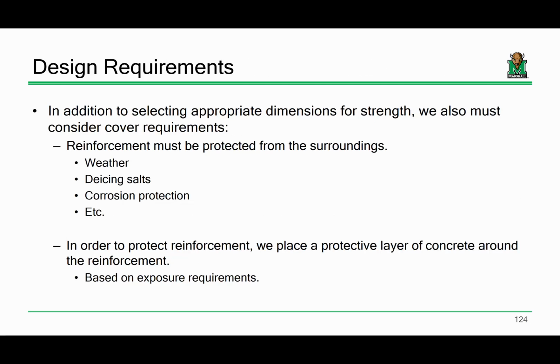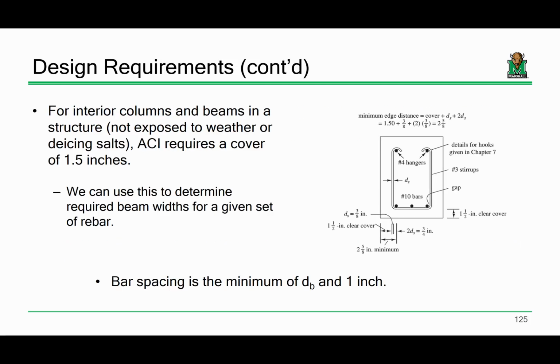The issue that I want to mention now is the issue of cover. Okay? So has anybody ever done any work with concrete or anything? Does anybody know what cover is? What is cover? That is exactly right. It is the amount of concrete outside the rebar. In other words, if you have a beam like this, you never put the rebar right on the edge of the beam. You embed it a bit.